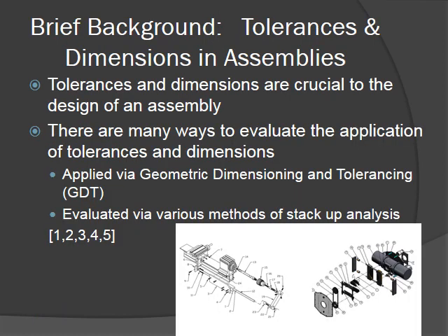So understanding the importance of tolerances and dimensions and the fact that they are directly related to how well our assemblies go together overall, and the fact that we want all of our assemblies to go together and function properly and as expected every single time, we see the importance placed on tolerances and dimensions. But we need to know how to apply those tolerances and dimensions, and that's done through a framework called Geometric Dimensioning and Tolerancing, or GDT for short. Once we use GDT to apply geometric dimensions and tolerances, we evaluate those by way of different analysis methods called tolerance stack-ups.